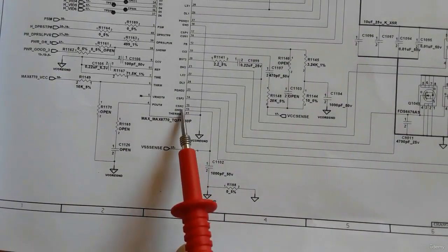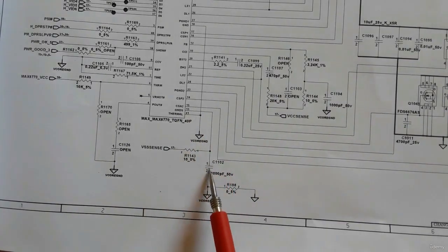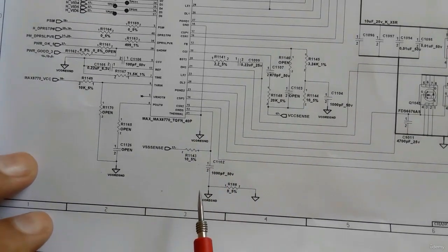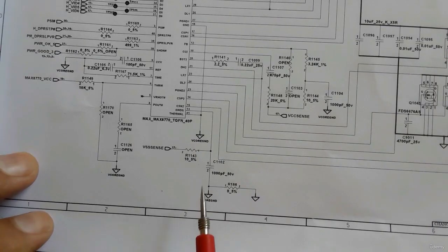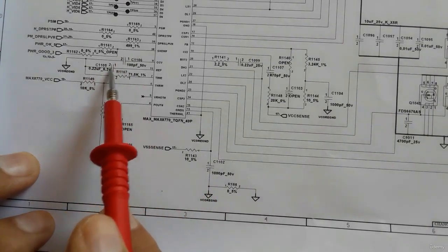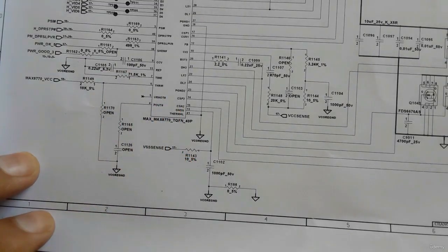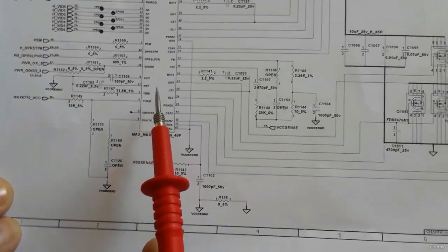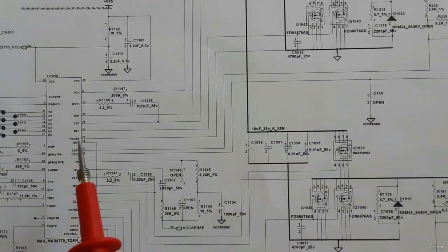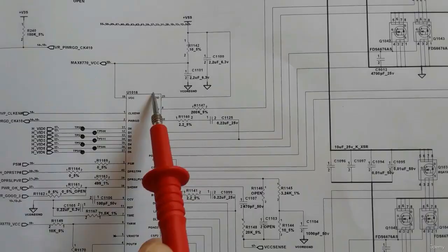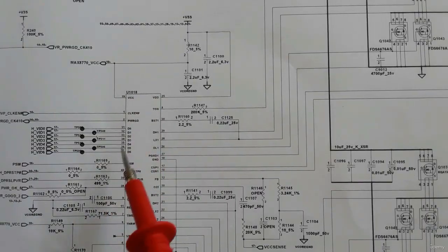So if you find any shorted capacitor, it means the power management IC is bad. So this is a technique that you can use to determine whether the power management IC is good or not. Just check the continuity between the terminals of a ceramic capacitor. If you find any shorted capacitor, it means the power management IC is bad.